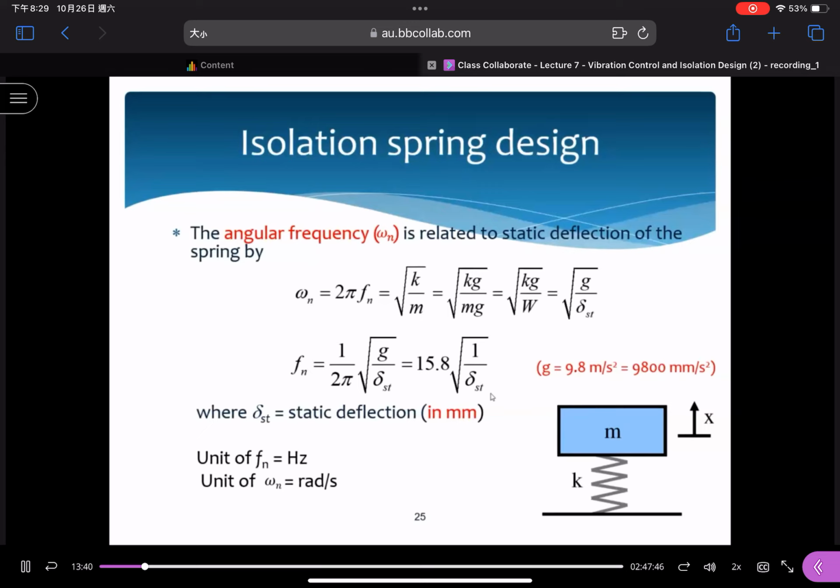Any problem? Please bear in mind that this is an exponential function. The power is in terms of zeta, the damping ratio, omega n, the natural frequency, and t is time. We still have another term, the harmonic term. In the harmonic term, what is omega d? Let me explain to you later on. t is time. And how about phi here? Phi is the phase angle.